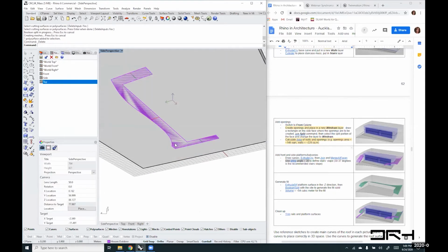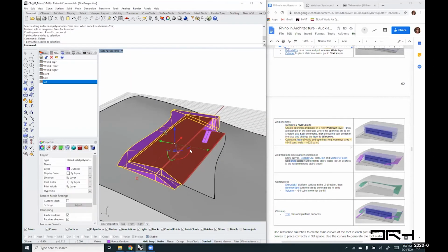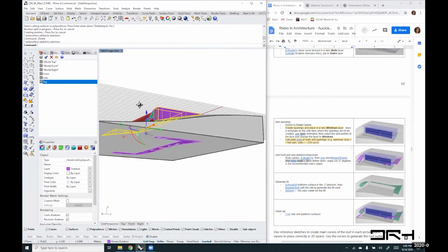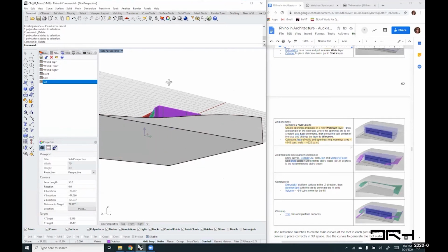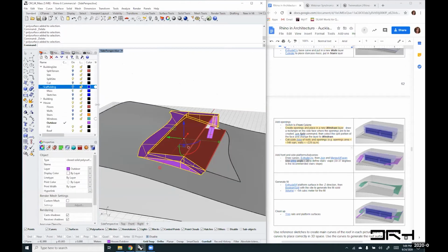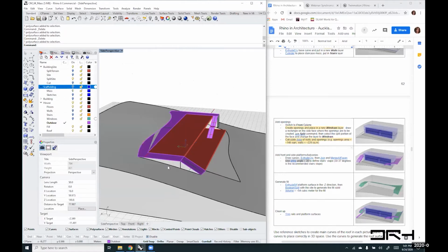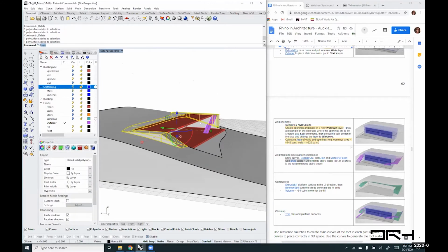This part, we don't need it. And there is another part which is inside the site. And there is the last part, which is that fill part that we will actually need. So I'll just select the other parts and delete them because I don't need them. All we need is this, and we can move it to the fill layer. Okay. So that's the kind of fill that we needed, and we can measure the volume of our fill, and it's roughly 46 cubic meters here, or 47.